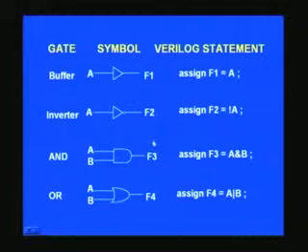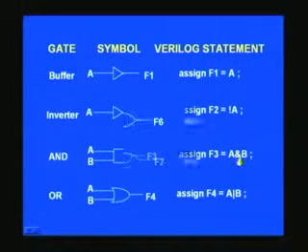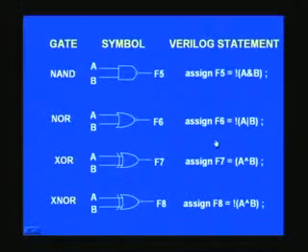And if you want to do AND or OR with two inputs, it's once again as simple as that. What you need is one more symbol you have to know. It's an ampersand and this vertical slash here. This is for OR, this is for AND. And likewise, whatever gates you have already derived, you can get its inversion. For example, a NAND can be derived from complementing AND. So what you had as A and B earlier, use the same inversion signal here, and so is the case for NOR. Once again you see inversion here, and for exclusive OR and exclusive NOR, once again you see the inversion, and for exclusive OR the symbol is hat.